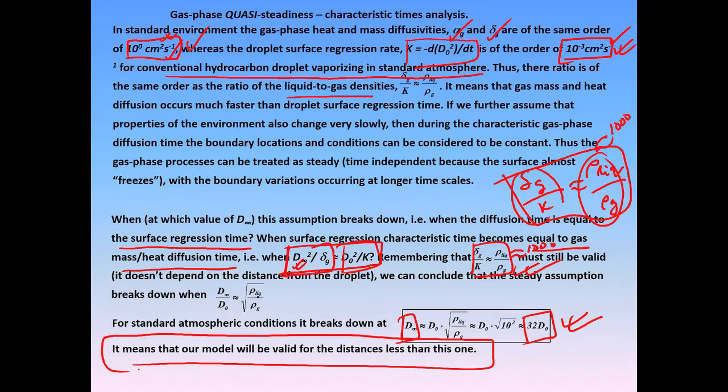So, this d square law is very powerful, but it comes with its own caveats, that these are the assumptions that we have stated, and we have assumed that it is a liquid vapor. Of course, if the difference between the densities of the liquid and the gas is very small, for example, if you go to supercritical types of cases, that could be very small. In those particular cases you cannot assume quasi steadiness. So, be prepared to understand what assumptions are applied and why they are valid. That is an important part of this argument.